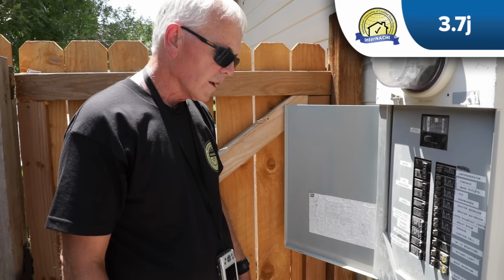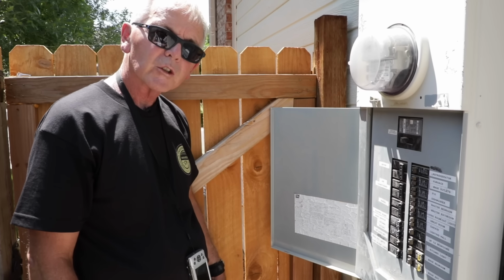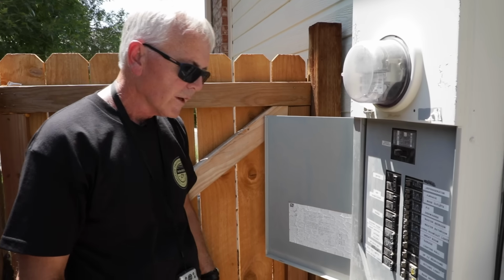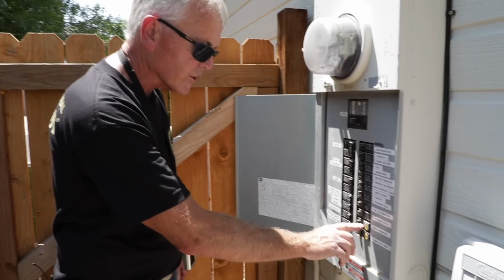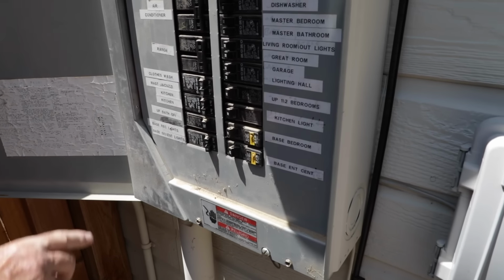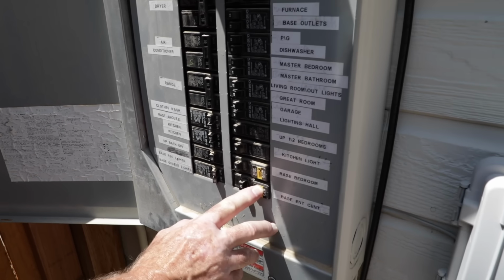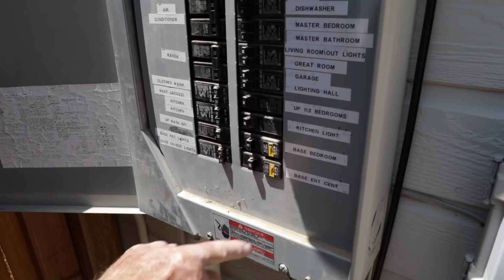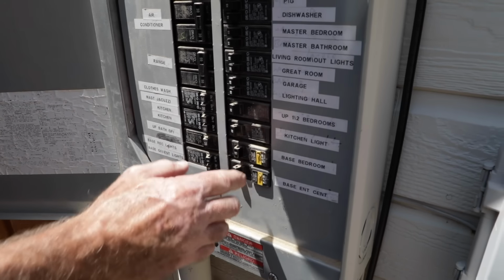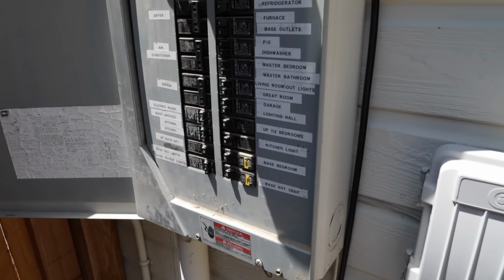Now we're going to cover the representative amount of switches, receptacles, light fixtures, and AFCI protected receptacles. And in this case, our AFCI breakers are located in the main distribution panel. So it's going to be easier for me to just test these from here, with the test button. They both tripped as they should. Now I'm going to do a reset. They both reset fine. Now let's move inside.